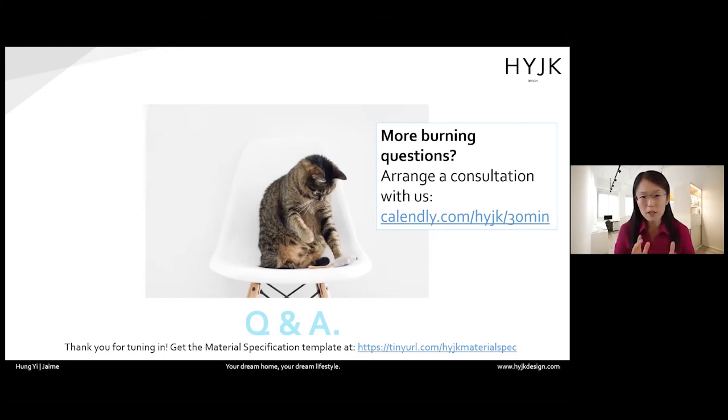But if you have marble in your homes, do take note that you should seal it, especially if you have dogs and cats or other animals that will vomit, pee, poop around. It's very, very important. Or even if you don't have that, one of our clients played mahjong overnight, and then they spilled coke, and there goes their marble, about 1 square meter worth of marble that they have to change. So it's very important for marble that you seal it. It's not easy to maintain.